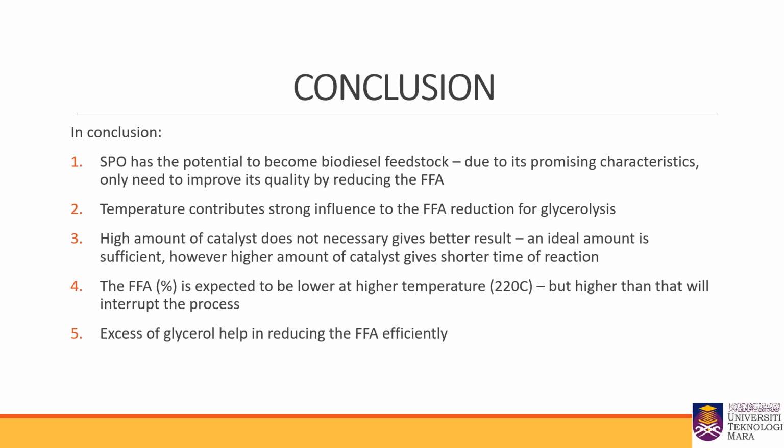Actually for the FFA, I think the best one is 190 to 200 degrees. We cannot go higher than that as it will interrupt the process. And we can say that excess of glycerol helps in reducing the FFA efficiently.